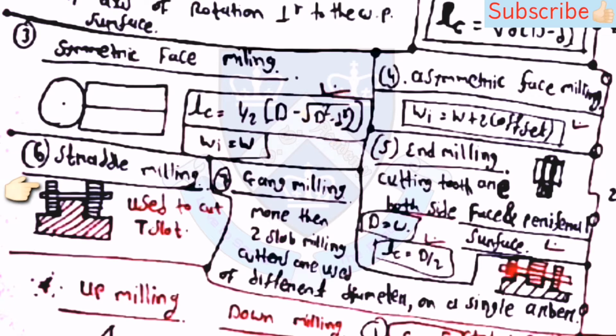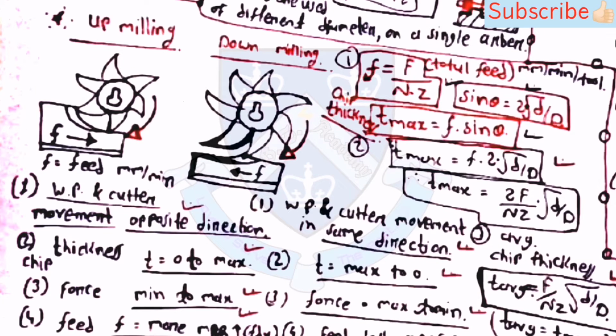Then straddle milling is used to cut a T-slot, and in gang milling more than 2 slab milling cutters are used on a single arbor, so these types of operations can be made. So these are the types of milling process. Then there are up milling and down milling processes.